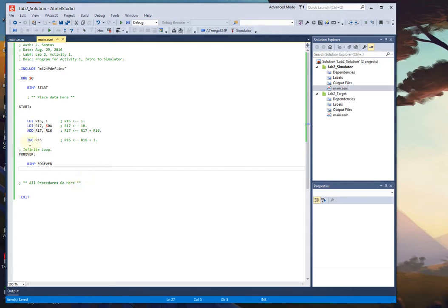They should not be accidentally run into by the microcontroller. So an infinite loop prevents runaway code. It also ensures that your program is still in control of the microcontroller, and it keeps the microcontroller in an alerted state so that it can always respond, for example, to external events such as external change interrupts on the external pins. This is very common in embedded system software.